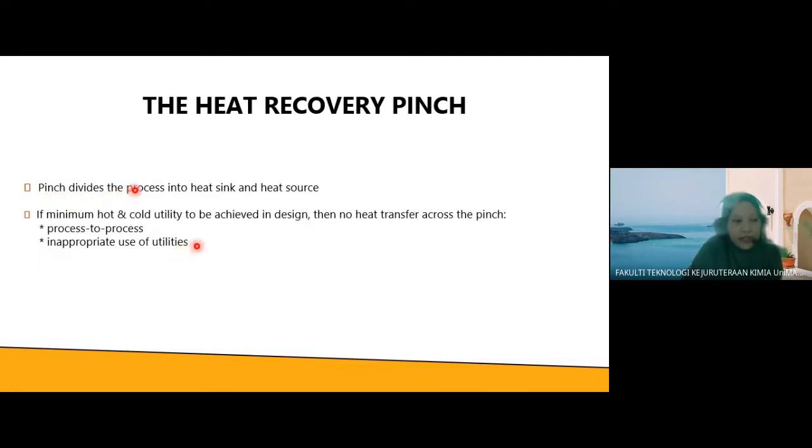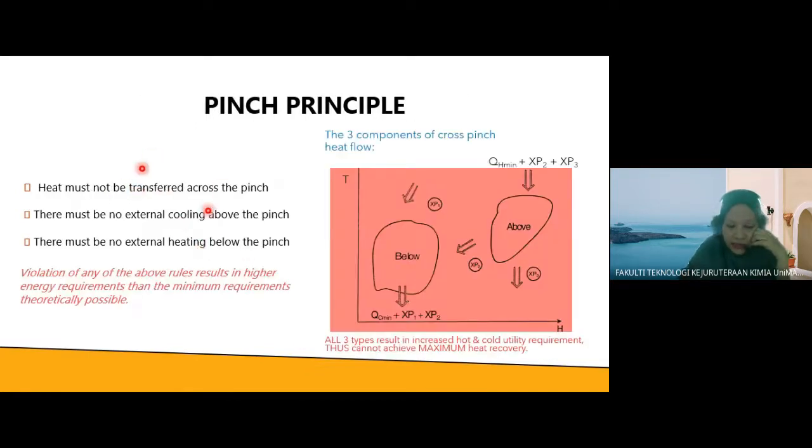What does it mean by inappropriate use of utilities? You must not have external cooling above the pinch, and you must have no external heating below the pinch. This statement.